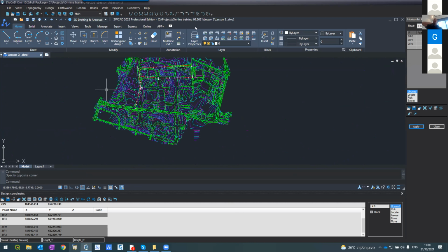Okay, there's one here. What is the criteria for the length of the vertical curve? Oh, it can be speed, but in this case, it's not the speed. It's what I saw, because I'm connecting to some kind of paved road. So I used the same criteria you saw to create my profile, the vertical curve to the existing ground level.